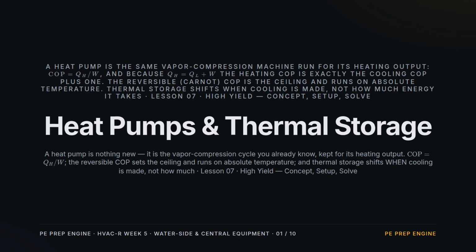Week 5, Lesson 7, Heat Pumps and Thermal Storage. This is a lean lesson because a heat pump isn't a new machine. It's the same vapor compression cycle from Week 3, run for its heating output. We'll define the COP both ways, show why the heating COP is exactly one above the cooling COP, set the reversible ceiling on absolute temperature, work one clean example, and treat thermal storage as a load-shifting concept.